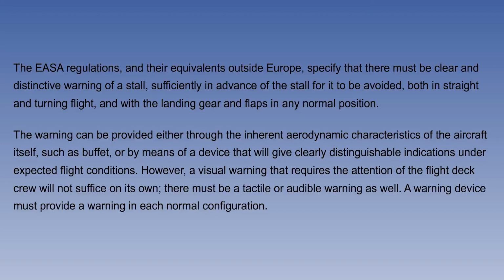However, a visual warning that requires the attention of the flight deck crew will not suffice on its own. There must be a tactile or audible warning as well. A warning device must provide a warning in each normal configuration.